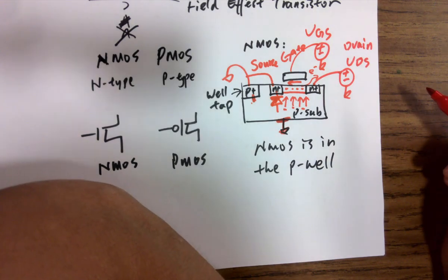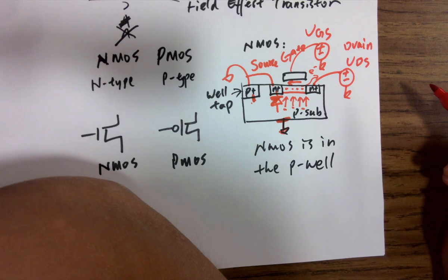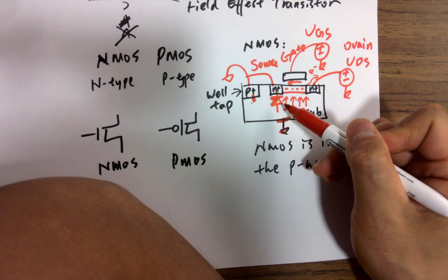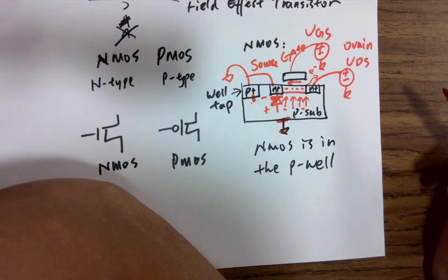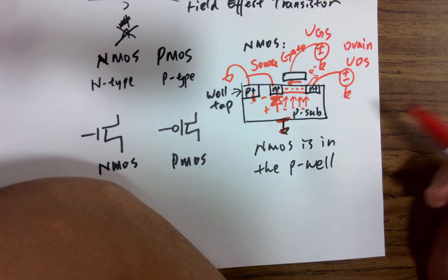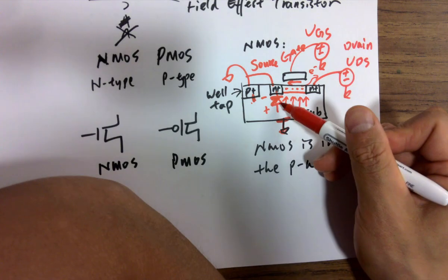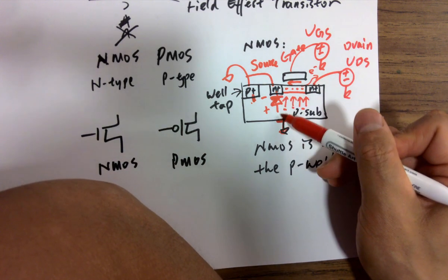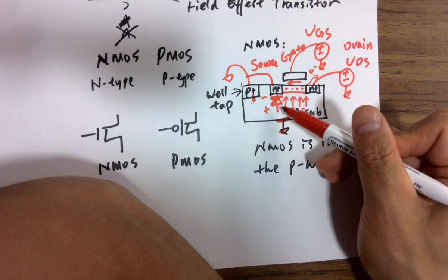So sometimes if you accidentally got the P sub at a little bit higher voltage than N, what's going to happen is the diode will be forward biased. You're getting a plus and minus voltage across a diode. What's going to happen? Do you need this diode? It's undesired. Since you put an N plus in the P well, it just forms a PN junction there. It's a diode.